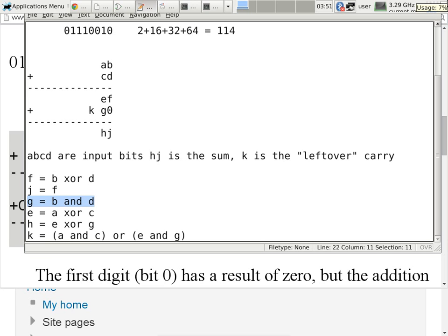If you were to add a third column, would you just add another full adder? That's correct. So if you want to have a 3-bit by 3-bit adder, I'm just going to draw the picture. I'm not going to use the equation, because once you know the construct of a full adder, you just put on another full adder here. It takes the carry out from the previous digit as carry in. It takes the 2 bits as the input, so that forms the 3 input pins into a full adder. The output is coming here, and then it has its own carry output to potentially the 4th column.